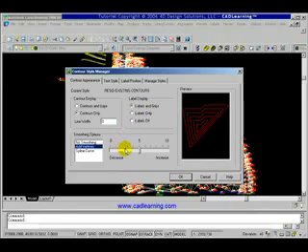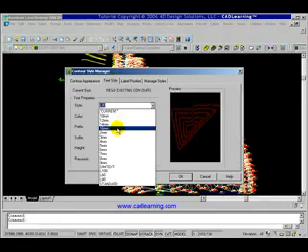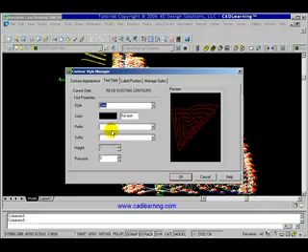We have some options for smoothing. We can select no smoothing, and the contours will be quite angular, or we can add vertices and some smoothing. We'll do that and keep the setting right in the middle at 5. For the text style, we're going to select a 2mm style. For a color, we're going to type in 30, and we'll change the precision to 1 decimal place.